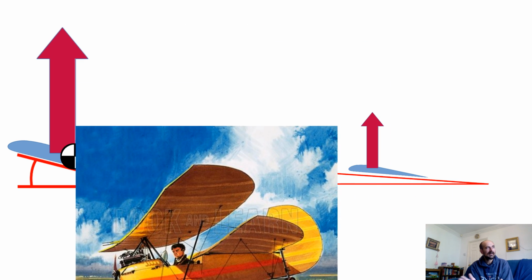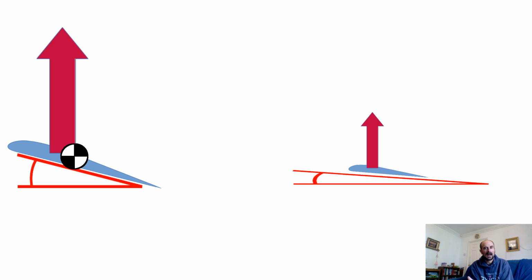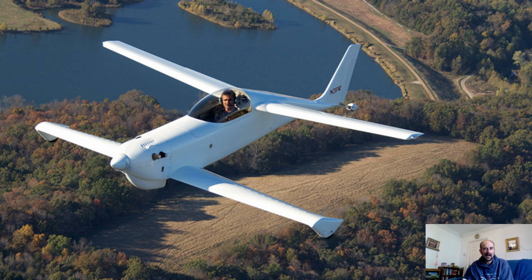You're not losing this performance directly by having the two surfaces effectively fighting each other, but if you're making, for example, a tandem wing, you're limiting aspect ratio and the span of the total thing, because you've got to split the lift between two wings rather than making one really efficient wing.